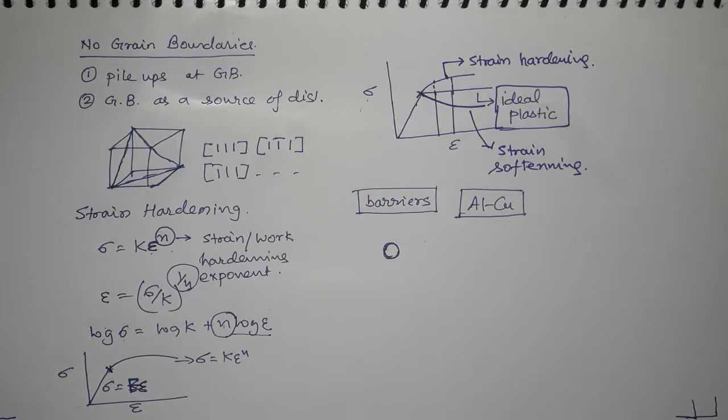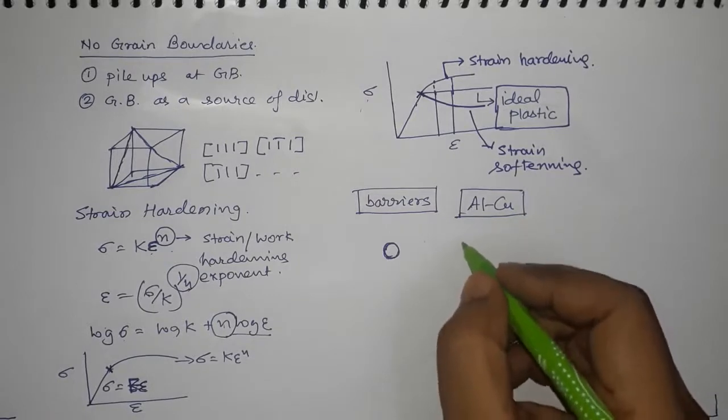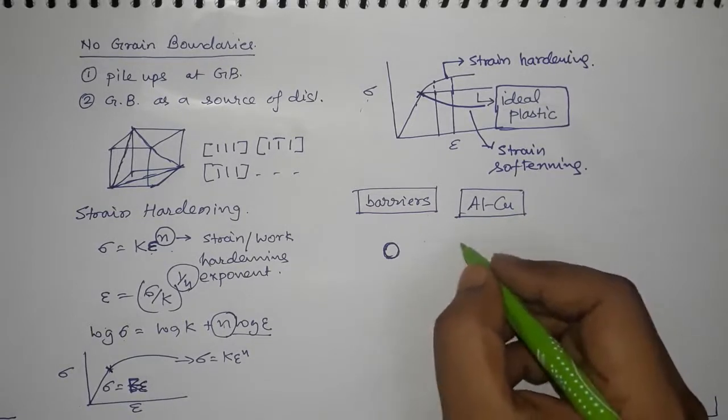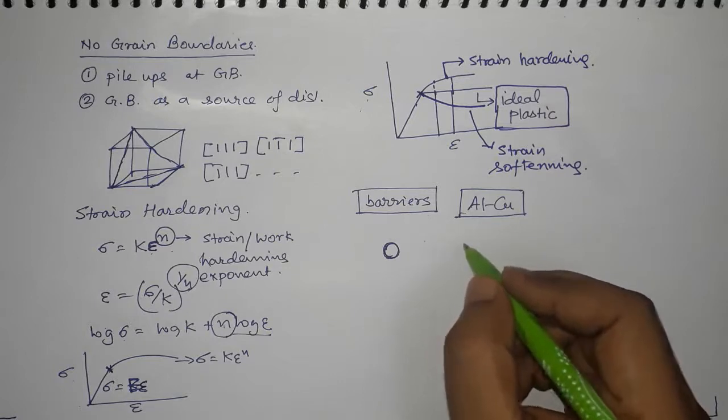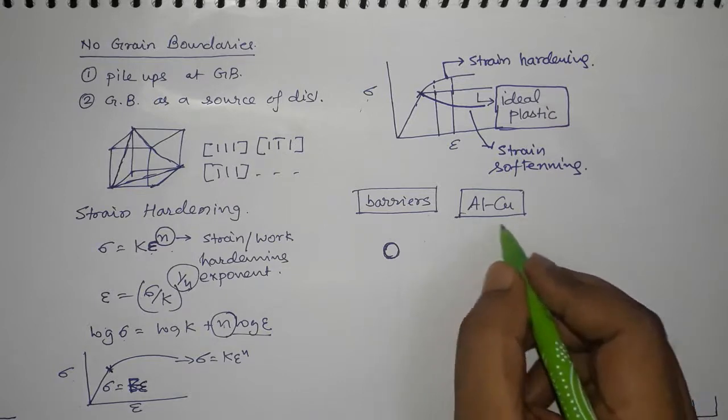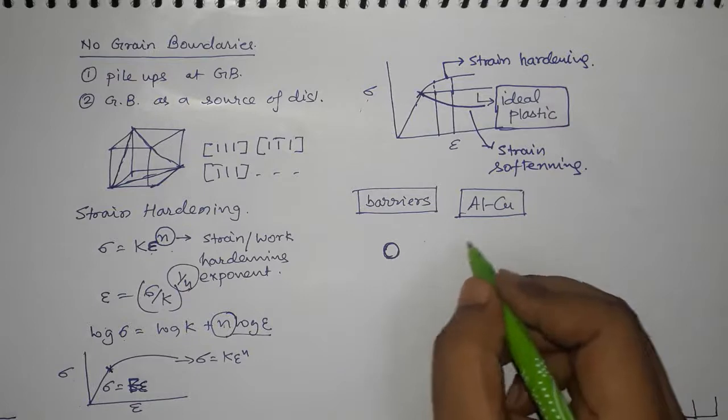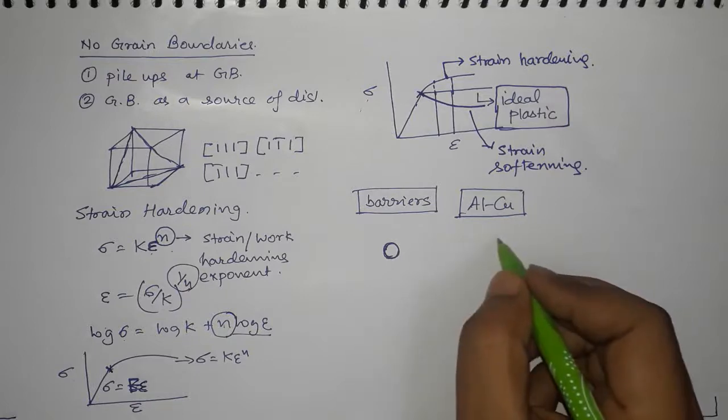Then more and more copper will deposit there, and that will be a kind of uphill diffusion against Fick's law, where atoms diffuse towards the direction where the concentration of that atom is already high. Now copper will start making its own crystal, but that will not happen in one stage. It will take a lot of stages to reach there.